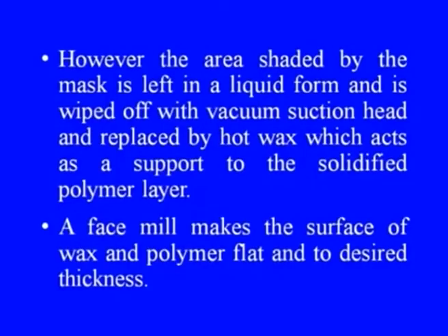However, the area shaded by the mask is left in a liquid form and is wiped off with vacuum suction head and replaced by hot wax, which acts as a support to the solidified polymer layer.